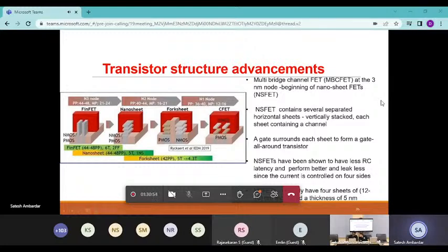So these are some of the new transistor structures. Nanosheets are the new structures. These are very thin structures, and we can go up to 2 nanometers. We can realize with this 2 nanometer technology node, and because of the nanostructures, and then the fork sheets and the complementary field effect transistors, these are the new transistor structures that are going to be used in the industry. So basically, in terms of the density of the transistors, a better control of the gate over the channel, and over the speed, over the leakages, over the short channel effects. So these are the developments in that direction.